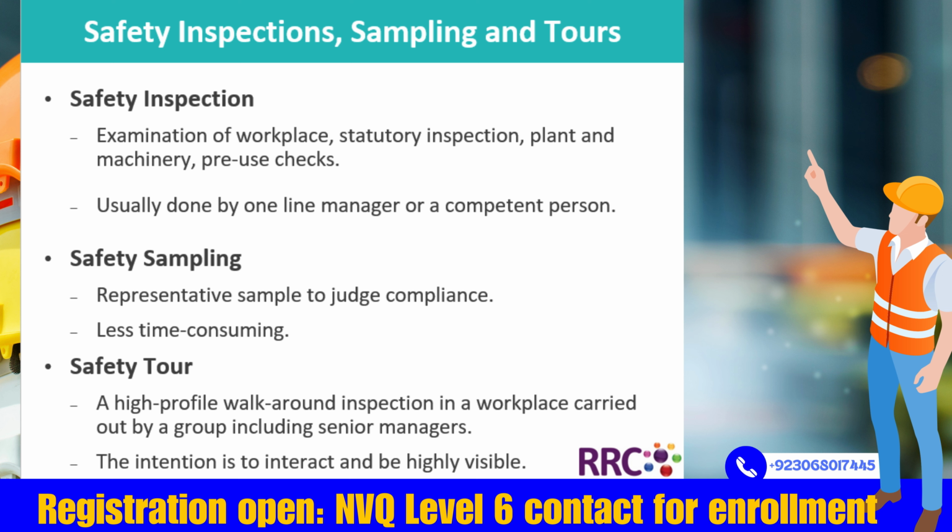The inspection process covers a range of items, from equipment and tools to workspace conditions like lighting and ventilation, to ensure everything is in compliance. For example, checking that machine guards are intact, fire extinguishers are accessible, and there are no exposed electrical hazards.